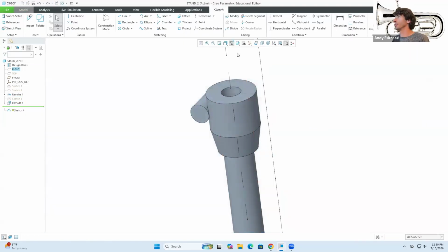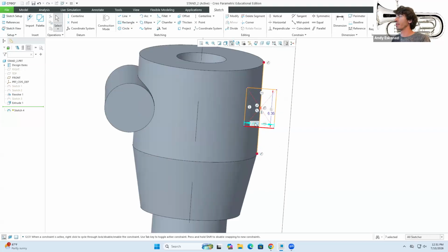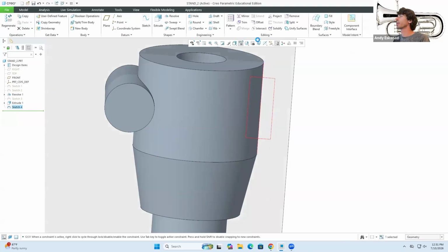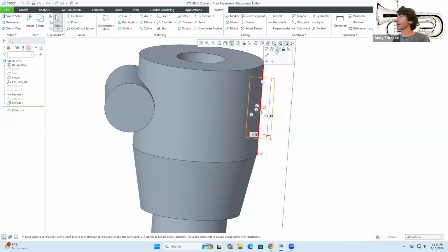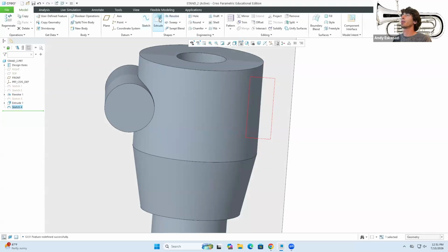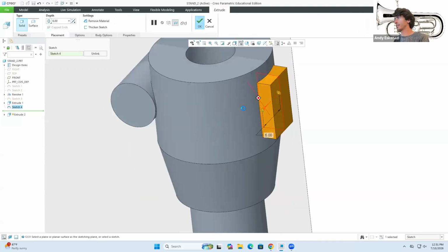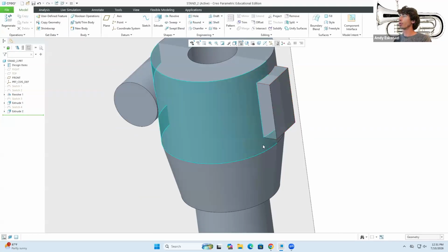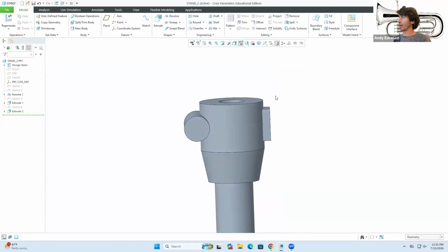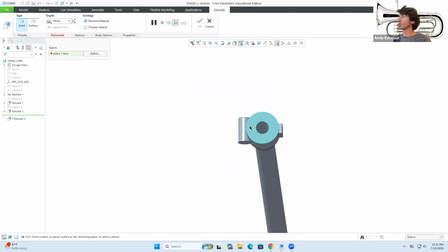And now we can do the exact same one here. So sketch, face, line. No, I do project that line, great, rectangle. I mean, we had said 4. We had said 10. Oh, by the way, yes, this is not gonna work because that line is not a construction line. Go to OK, sketch, symmetric, and I believe we had said 6. Good. So now this is the point where I'm gonna hide this, and I can do a sketch over in that face,